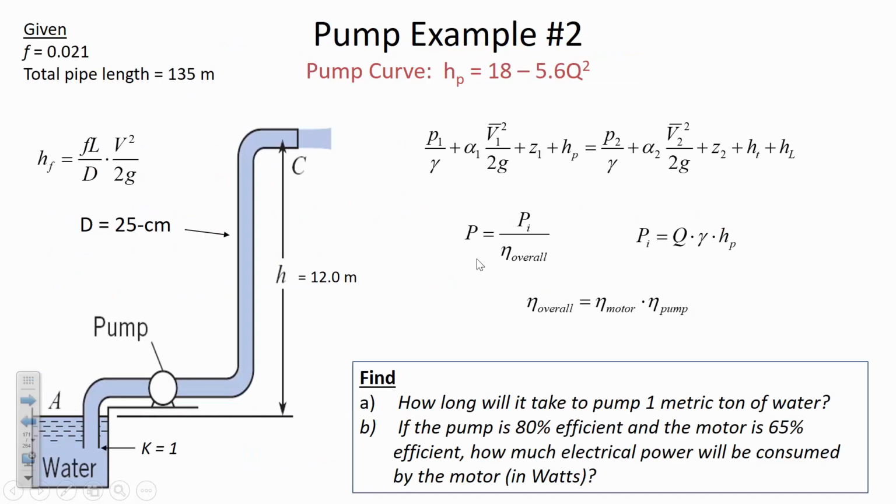All right. Just to refresh our memory and to kick things off, let's consider this system where, remember, we identify what the flow rate is going to be by setting the system curve equal to the pump curve. And every system can have a system curve generated just by rearranging the energy equation for the parameters that you've got.